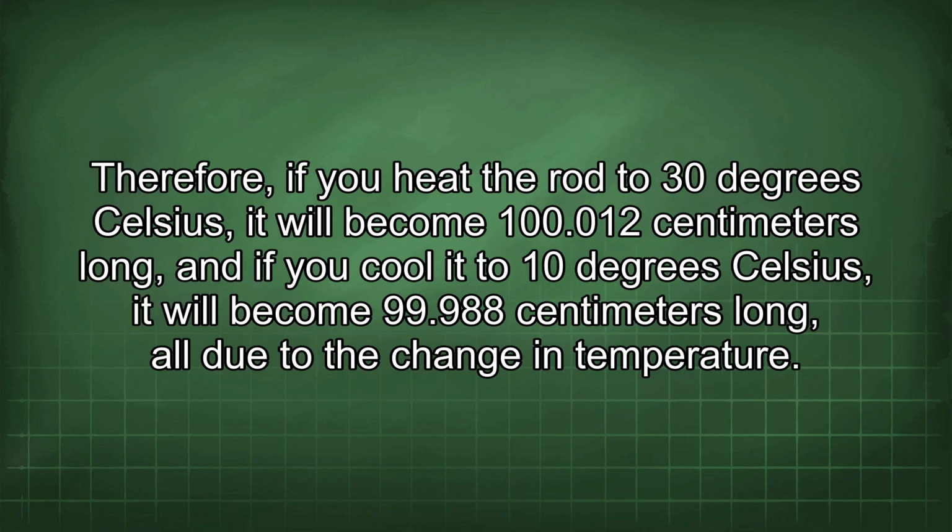Therefore, if you heat the rod to 30 degrees Celsius, it will become 100.12 centimeters long, and if you cool it to 10 degrees Celsius, it will become 99.988 centimeters long, all due to the change in temperature.